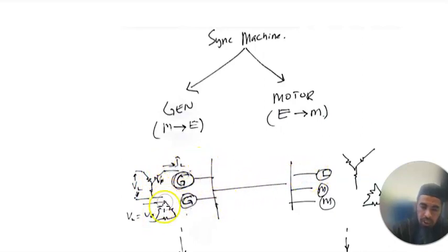If it is connected in delta, then V phase and V line are the same terminal values, but for your current, I line is the square root of 3 times I phase. So you sketch the related layout or scenario, then write down all the related equations on the sketch.